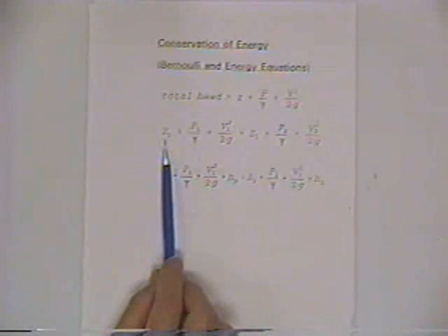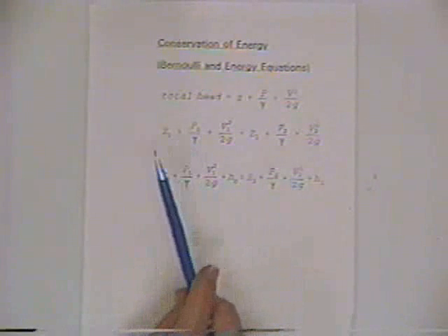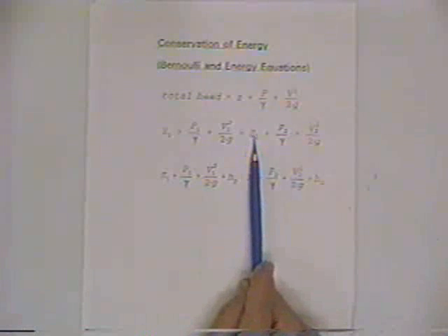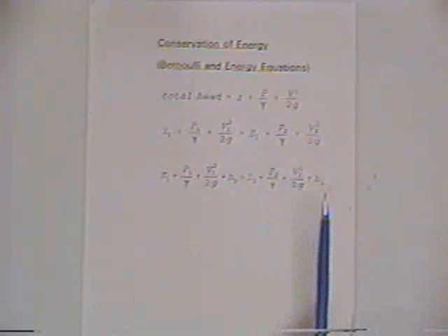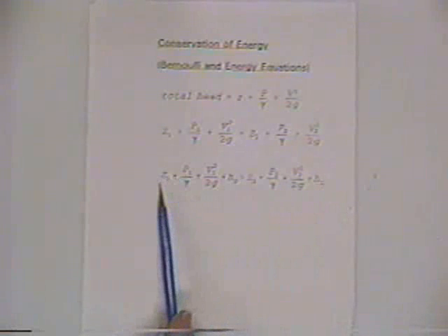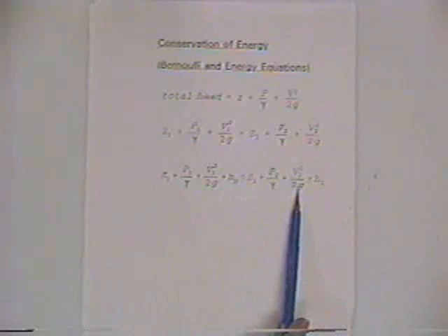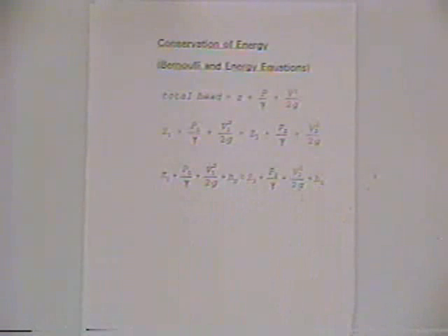And if we write Bernoulli's equation for an ideal fluid without frictional resistance or head losses, we're just saying the elevation head at one location plus the pressure head, same location, plus the velocity head at that location are equal to the summation of the same terms at another location, in a channel, in a pipe, or whatever. But in reality, in a non-ideal fluid, you have frictional resistance and head losses, as the hydraulic energy is converted to heat energy and dissipated to the environment, and so we have a head loss term. So we've got the total energy upstream is equal to the total energy downstream plus the head loss that occurs between the 2 points.